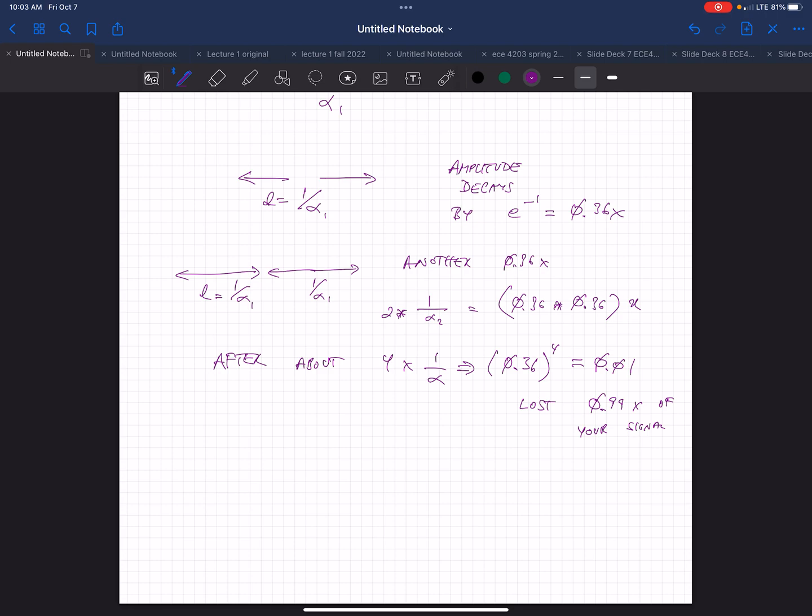So is the attenuation a really small value though? Yeah, if you're lucky. It seems like a big problem if you're dropping at an exponential rate. Yeah, for losses. But it does depend. It's a small number, but again, it depends on your frequency and your distance. If you're running a 10 gig transmission line, it won't be such a small number. You will lose a significant amount of your signal. People do not run those lines on printed circuit boards more than 2-3 inches, because you just end up with a big loss. It's not just a loss, but it's a big part of it.